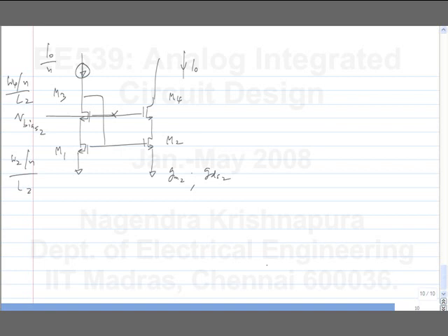So what are the small signal parameters of M1 and M3? Let's say this is GM4 and GDS4. What are the small signal parameters? This will be GM2 by N and GDS2 by N also. So everything is n times smaller. It is like taking one nth, cutting it up into n slices and taking one of those slices. We can discuss this in detail later, but what is the output noise?